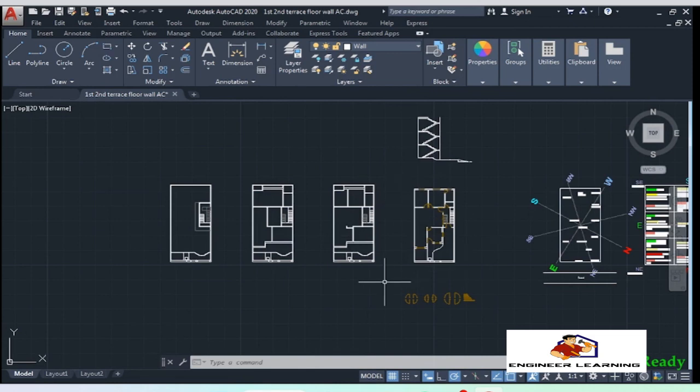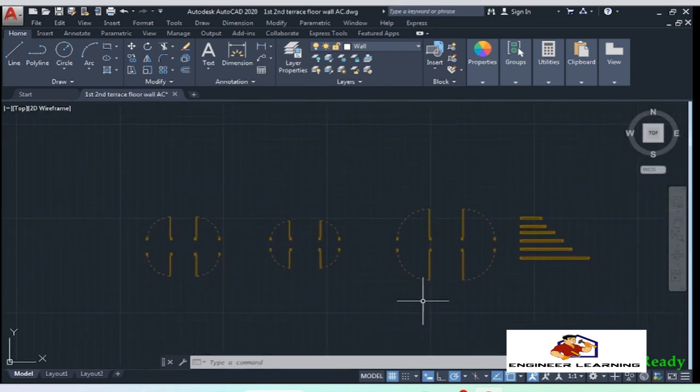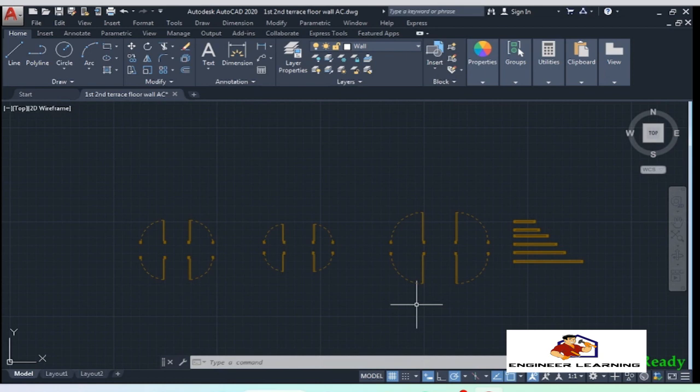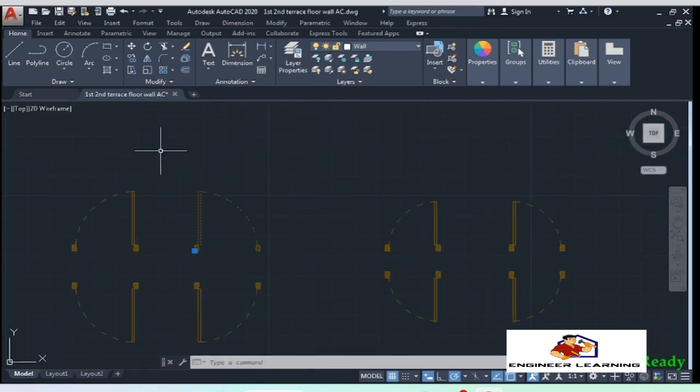What if we have to place doors and windows for a high-rise building having several flats at each story which change in size at each story level? This old-fashioned way of placing doors and windows is inefficient and time-consuming. So to deal with this, we have to take help of special features of AutoCAD called dynamic blocks. With the help of dynamic blocks, we can increase and decrease size of doors and windows with just one click. We can even flip the doors in any direction we want. So let's see how we can make dynamic blocks for doors and windows.